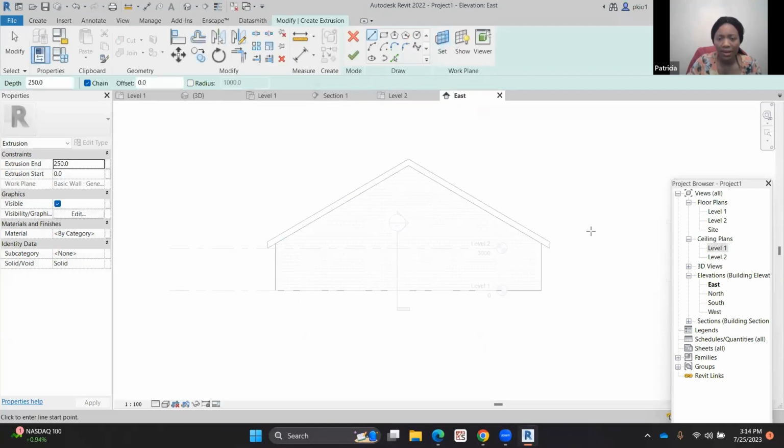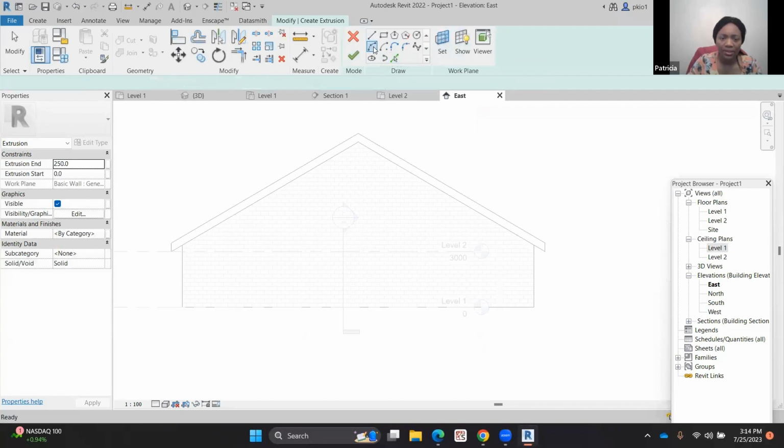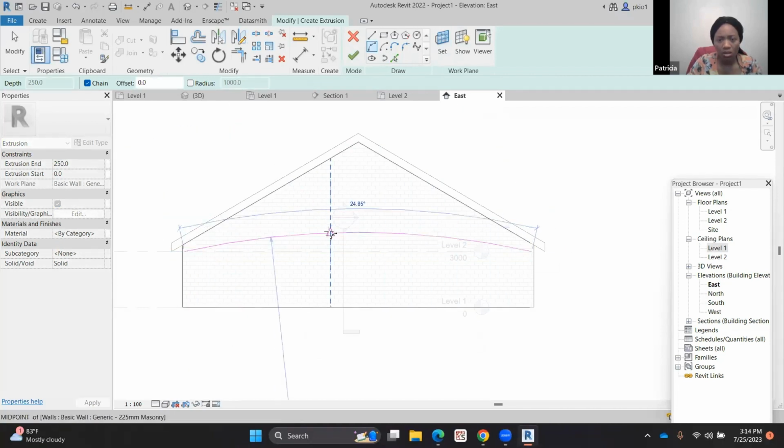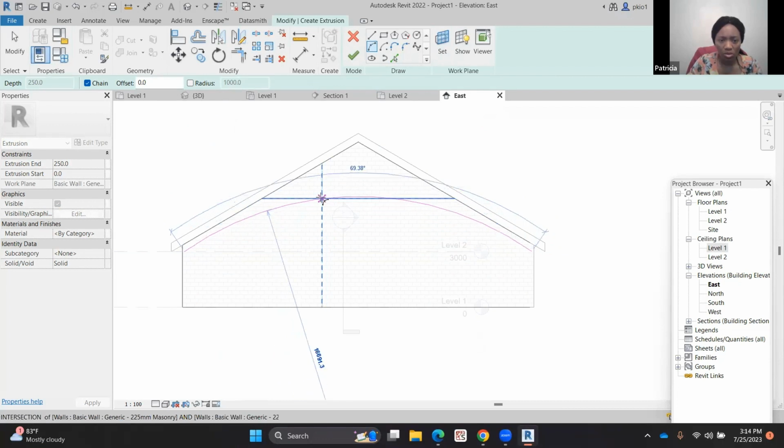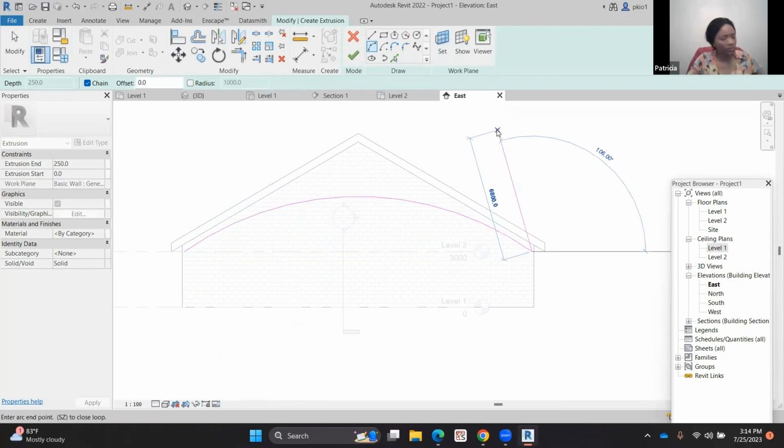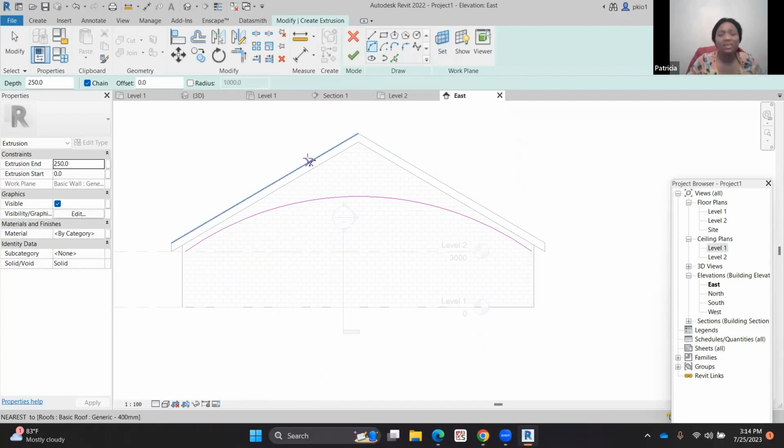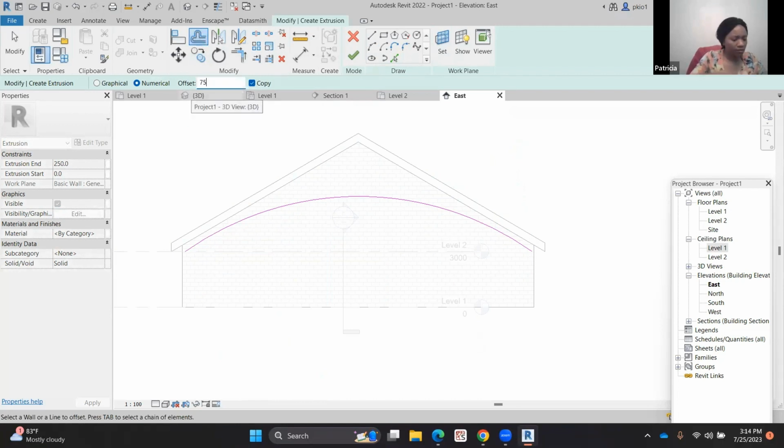So once it's open now, I can draw the ceiling using this tool. I pick a curved tool, and then if I go across this way, and then pull it up, this is going to be the ceiling. So I'm drawing the section of the ceiling now, and then go to offset and give it a thickness. 600 is too much, so let's say 75. And then if you put your mouse over the line, it will offset by 75.